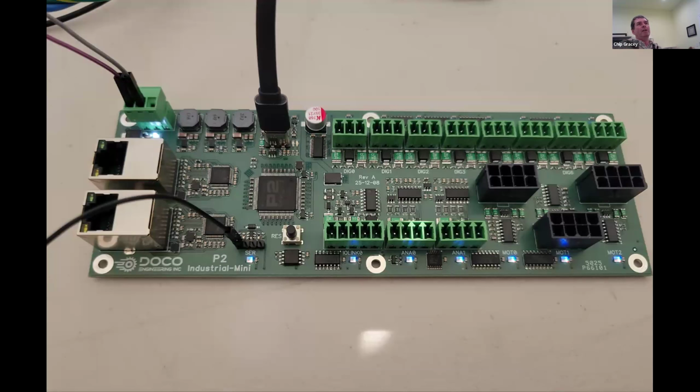So let's all now update our parallel 24-bit shift registers that we've been holding and promote those to the RGB outputs. So it's a nice little protocol. It's not complicated, but here's the trouble I had. That thing has a period all its own, right? Not just the bit timing, but the whole mode of, are we sending out a data bit? Are we in a little post 24-bit clear period? Are we in a refresh thing where we've got to tell all the LEDs to go?